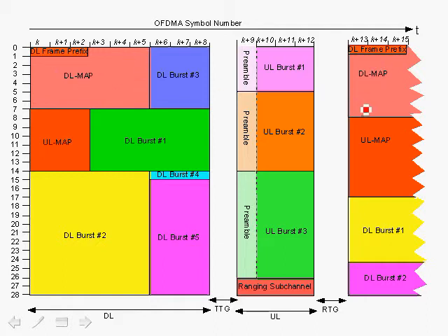Like if you notice on this slide, the downlink map has actually changed size. The reason is that if the data bursts for the subscribers change, then of course the size of the map describing those data bursts may also change. So this is a very important point. Also the uplink map. That's why in this diagram we've drawn them differently between the two downlinks. Very important point.